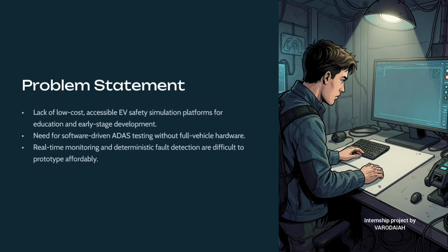This project helps us in detecting forward collision warning and blind spot detection, left and right, and we shall also use alarms and LEDs with a buzzer. If the time to collision is less than 5 seconds, a warning alarm is displayed, and if it is less than 2 seconds, a critical alarm is displayed in the EV dashboard.